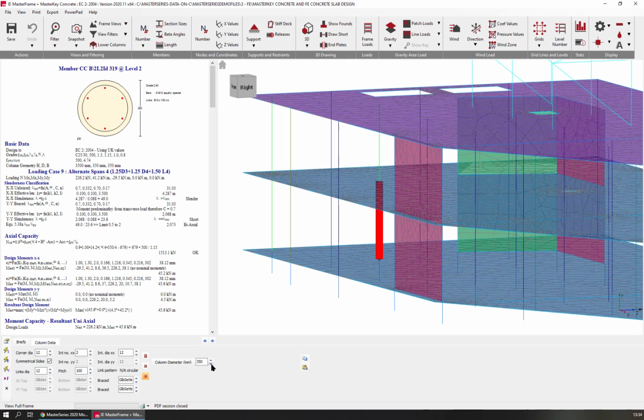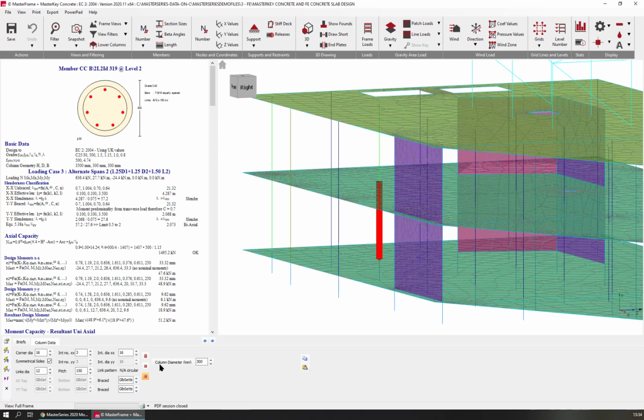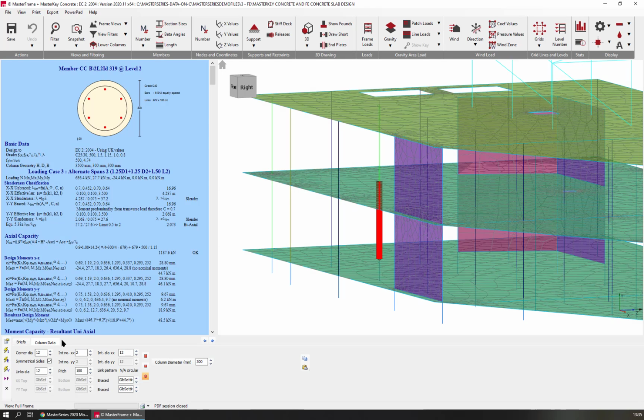Come down to a 300 column and size that, and at this point we'd need some extra bars, so we would consider pushing that back and auto size. That's better. 6 bars rather than having to go 7s, and 12s is all we need. So 350 at that. Would we get away with that?